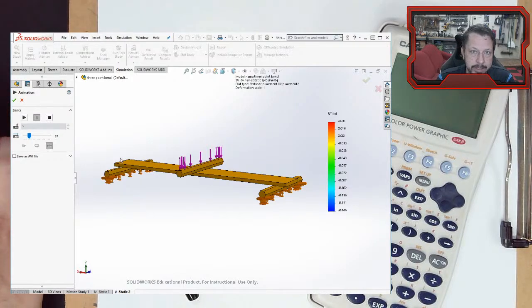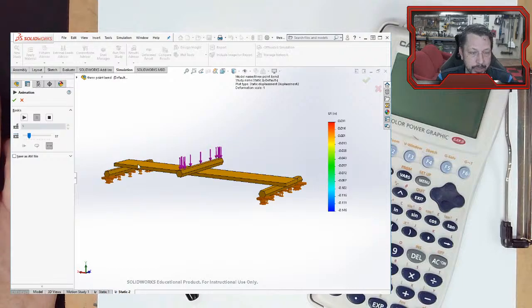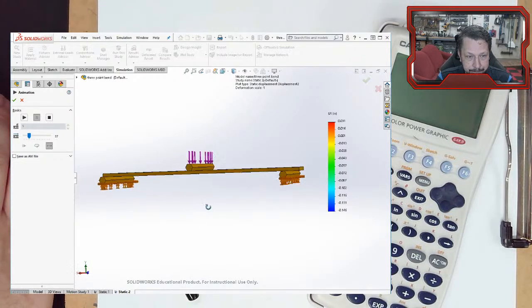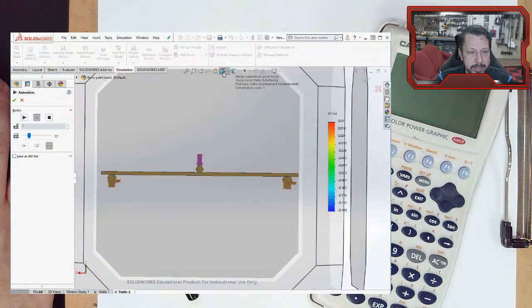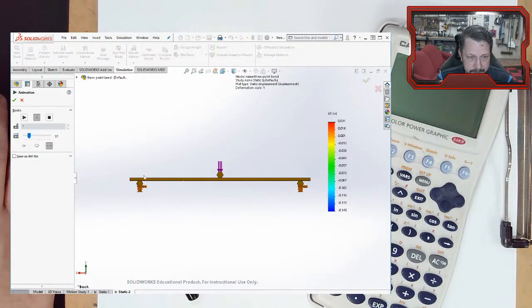You have your sample in there, and in this case we're just going to make everything out of some generic steel material. So we're expecting to get a modulus of elasticity somewhere around 29 or 30 million psi. How we're going to go about doing that is, let's zoom head on here, let's turn off perspective for a second, this looks a whole lot like the beams that we just dealt with, a simply supported beam with a load directly in the center of it.